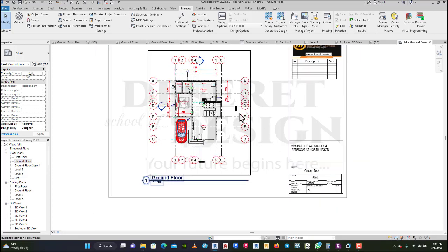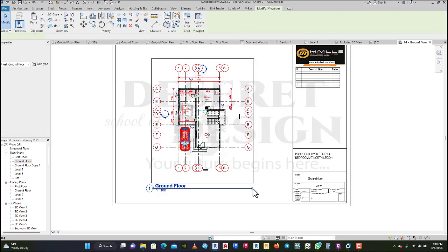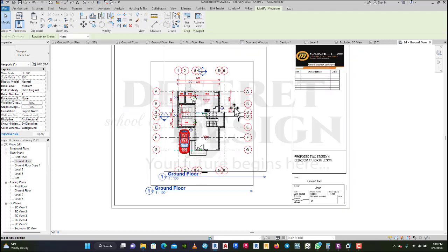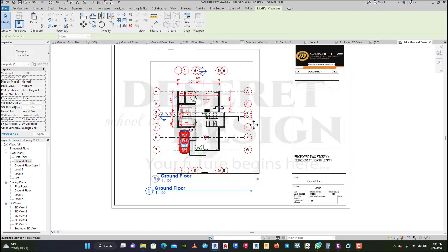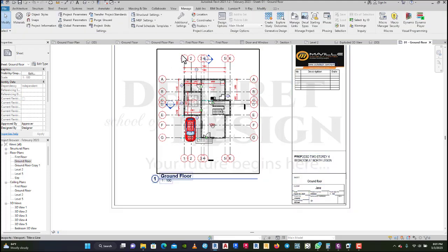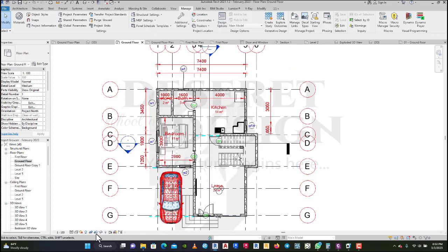Okay, so the simple way is to bring your thing onto the sheet. Then you can position it well. You just click and move it and position it well. Now make sure your crop region is off on your sheet. Otherwise, if that box is by the sheet, when you come here, it will also be showing. Okay. So every time you finish, put the crop region off.